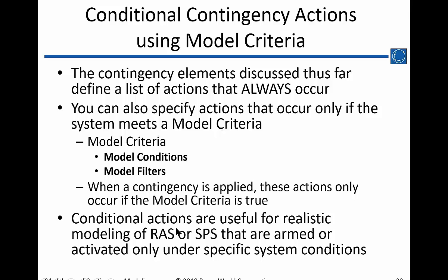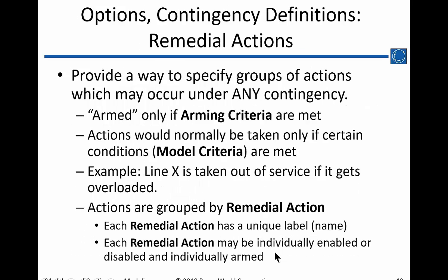We'll see that this is a useful tool for creating remedial action schemes or special protection schemes that are armed or activated only under certain conditions. So under maybe a certain loading condition or certain voltage profile, or whatever you can imagine as far as monitoring a condition and then arming an action associated with it.